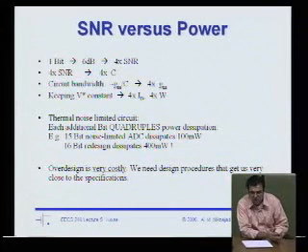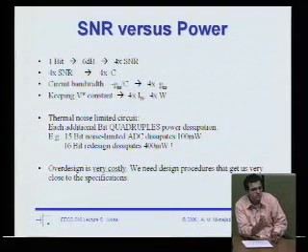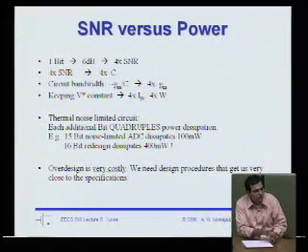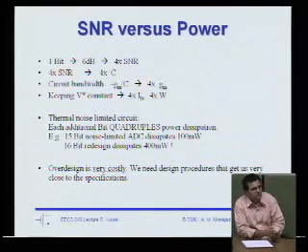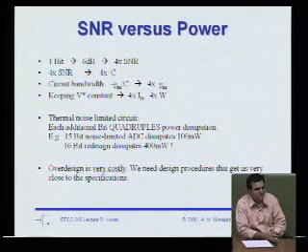So in our traditional way of thinking of SNR, it has nothing to do with bandwidth, but in reality, of course, it does, because the bandwidth also tells you how much signal processing capability you have. So you can come up with figures of merit to your heart's content. You might say, well, it should be SNR times bandwidth, right? That's a better figure of merit. Okay.